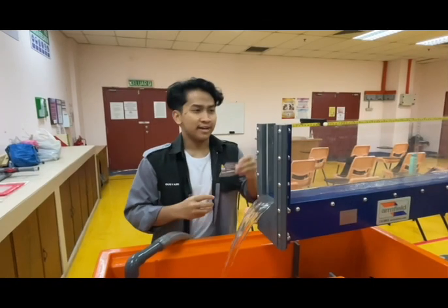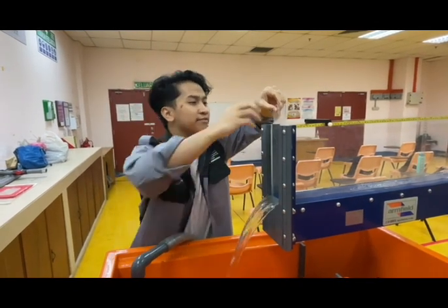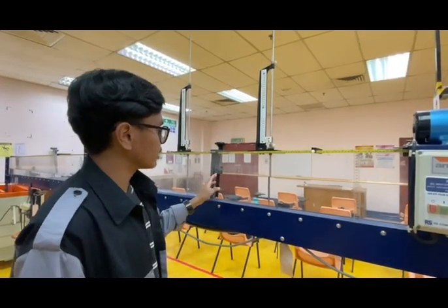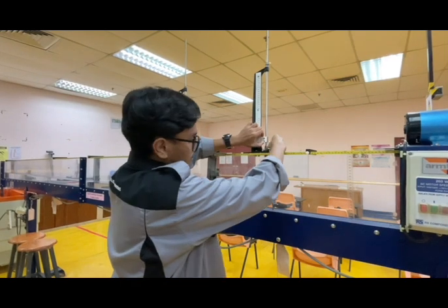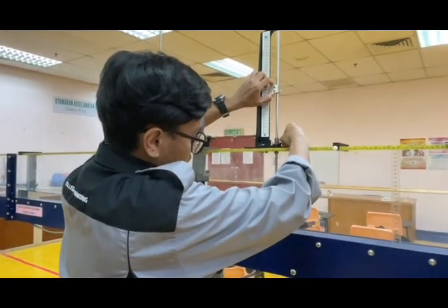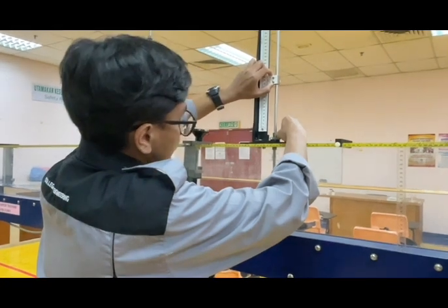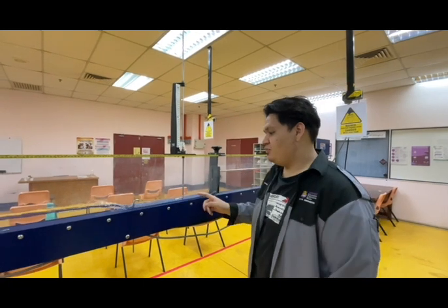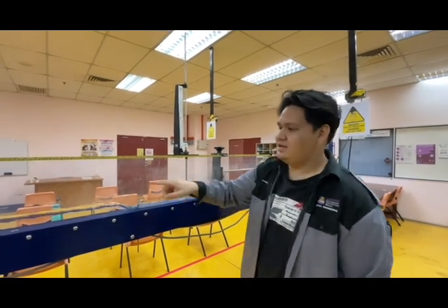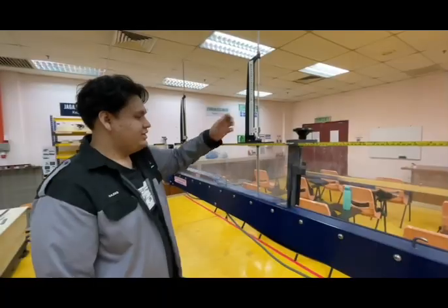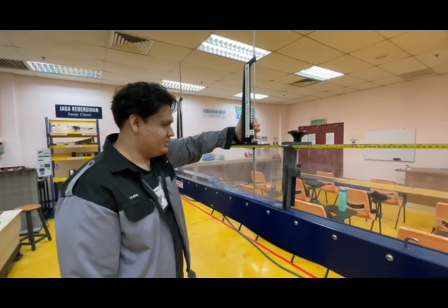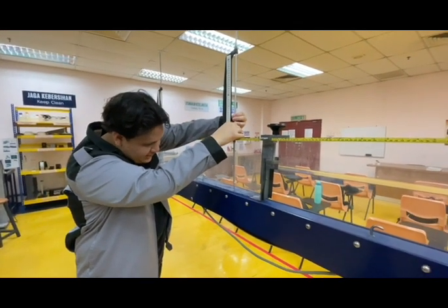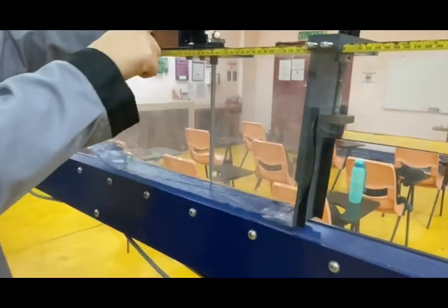After that, we place the tailgate at the rectangular flow channel. Then we measure the height of the water before the sluice gate. And we record the data. After the jump stabilized, we need to find the depth of the upstream and the downstream using the point gauge. Next, we measure the height of the upstream. We place the point gauge right after the water surface, and then we record the data at the point gauge.